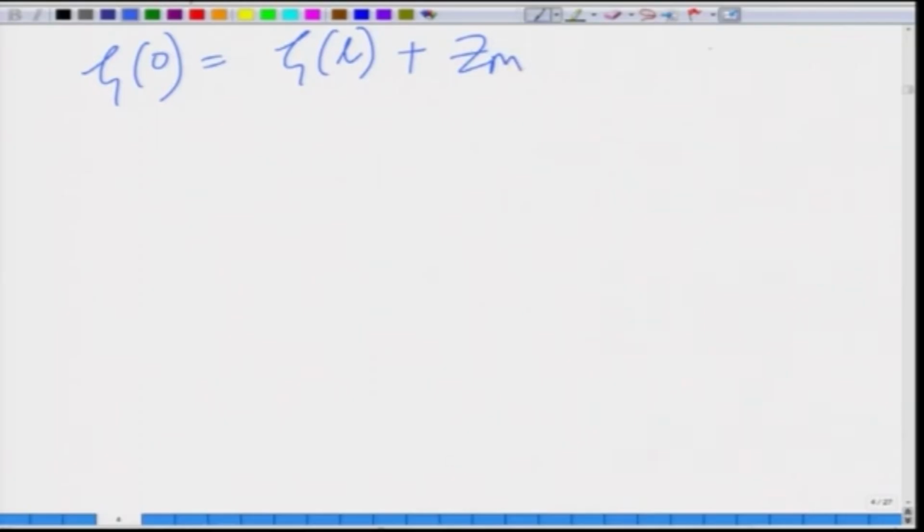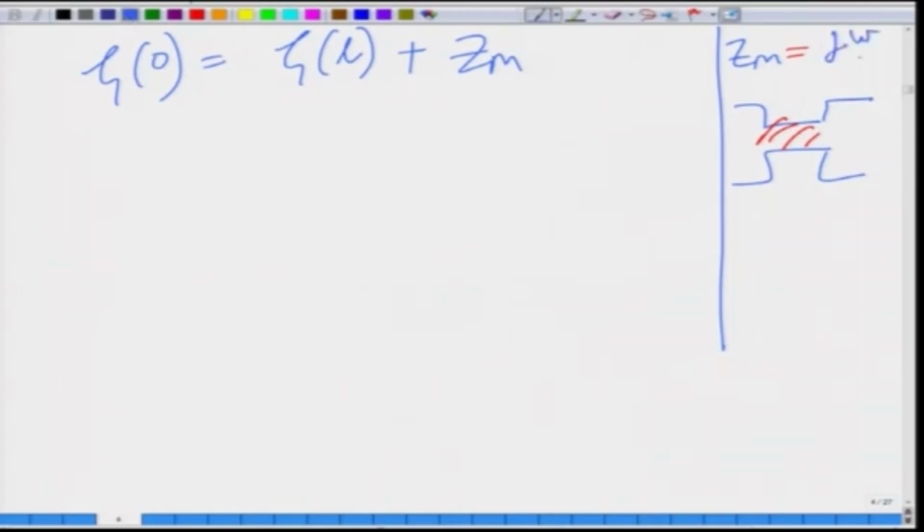So, that was clearly our inertance. If you recall, the inertance for a structure like this, a small tube sandwiched between two large cavities, the impedance or the inertance was given by j omega L by S, where S is the cross sectional area and L is the length.